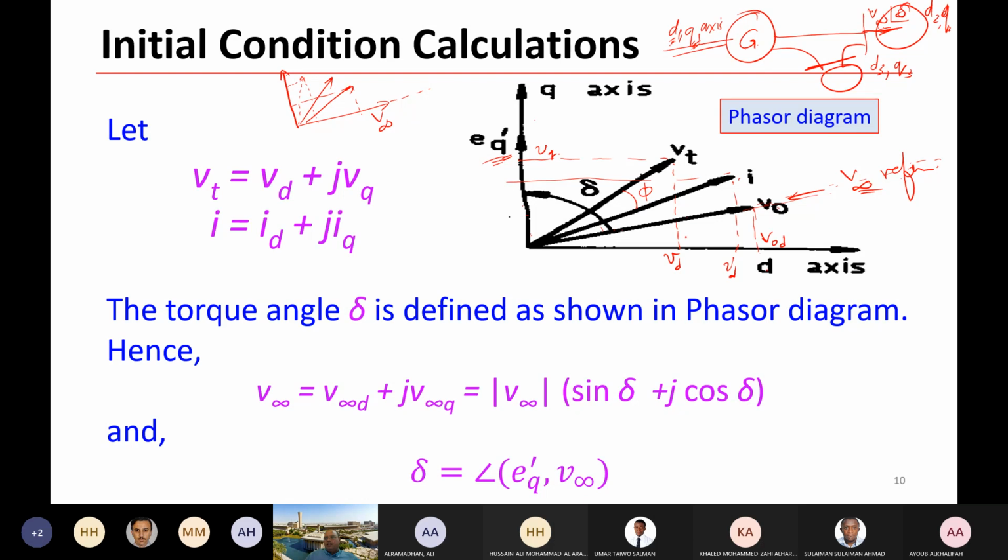Yes. In that case, you can either create a fictitious machine and relate the others to it, or if you have an infinite bus, you consider it as your reference. Then ID and IQ for this machine you have to project on the system reference.